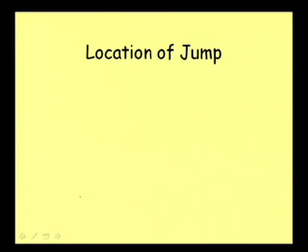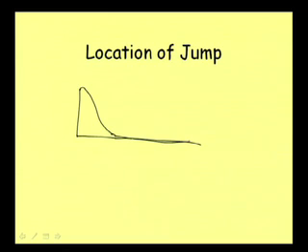Well, then another topic that is of importance is the location of hydraulic jump. As we have discussed, the location of hydraulic jump on the downstream of a dam, where the hydraulic jump will be occurring, is very important. If we can control the tailwater depth somehow, suppose it is low, tailwater depth low means the jump is getting repelled and it is occurring here. So, where it will occur, how can we determine?